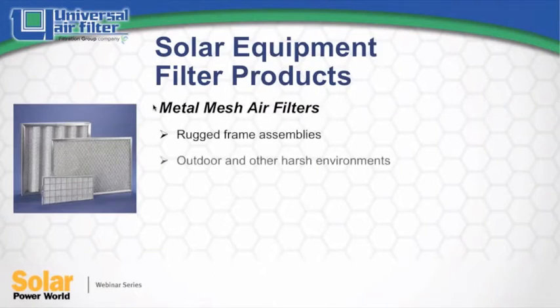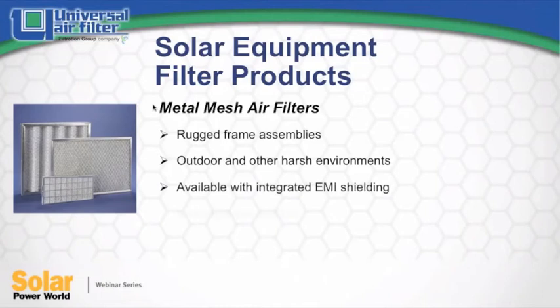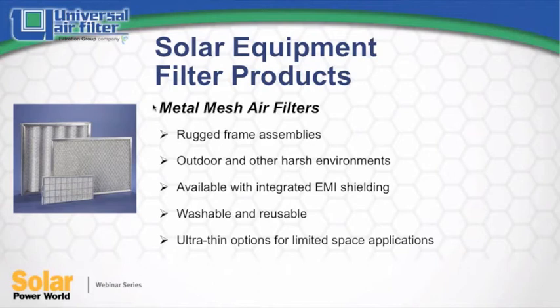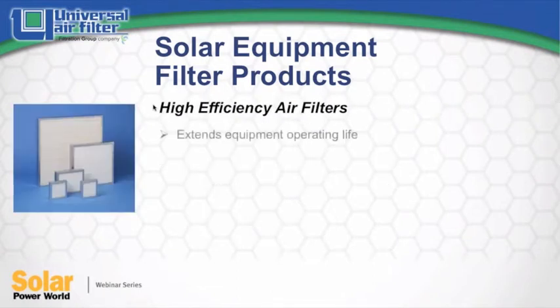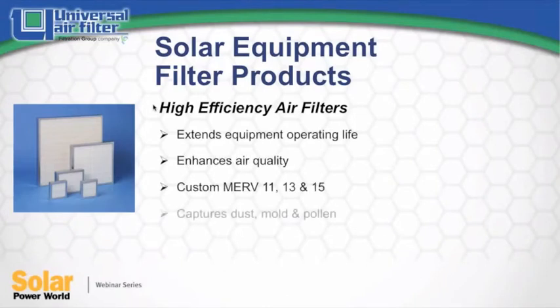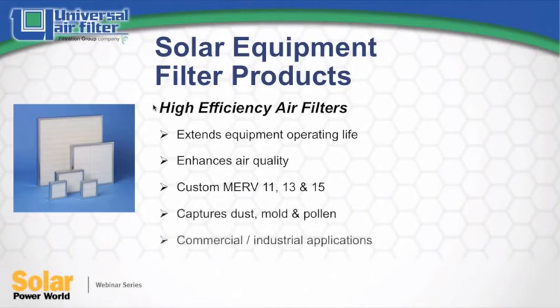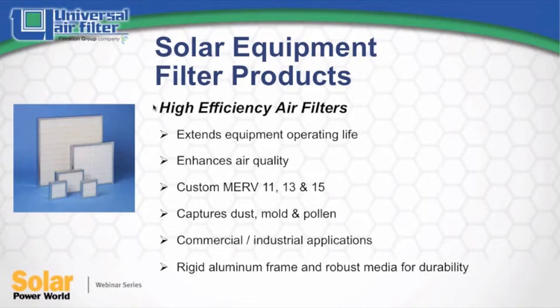Taking a look at some of the useful power gen filter products that are out there, all metal filters are most durable for the harsh environments experienced by power gen equipment, and they're also reusable and rugged enough to stand up to multiple cleanings. High efficiency filters are generally more expensive and not recommended for cleaning and reusing. However, sometimes equipment gets deployed in uniquely contaminated environments, and it's good to know the option is available to improve equipment protection using high efficiency air filters.